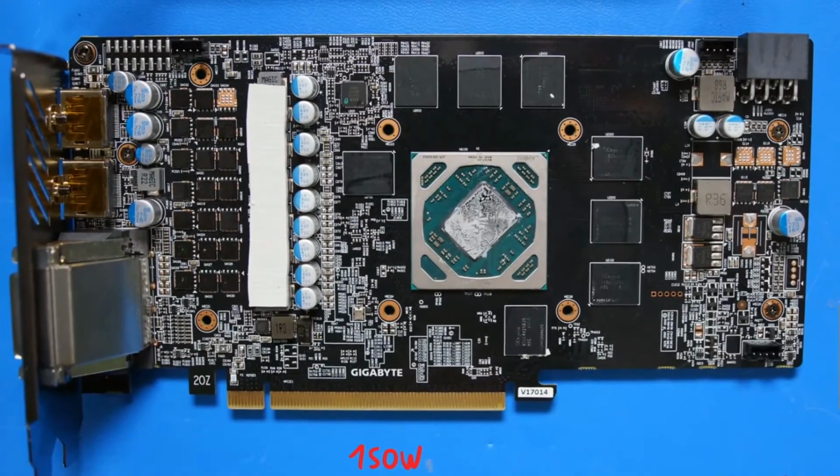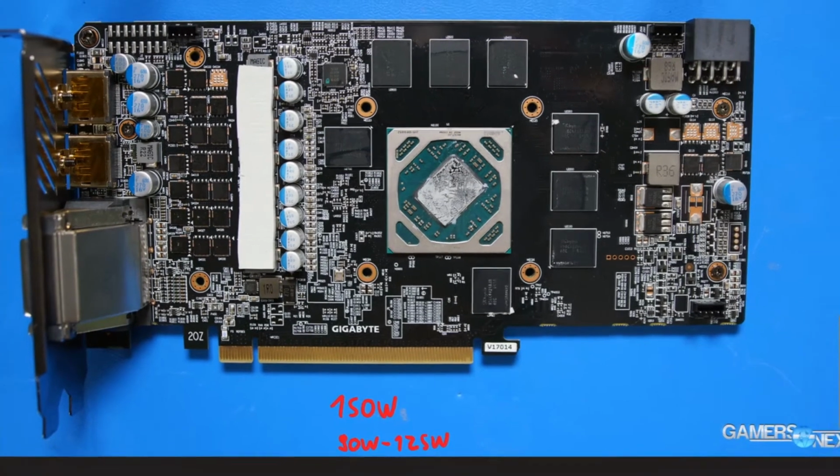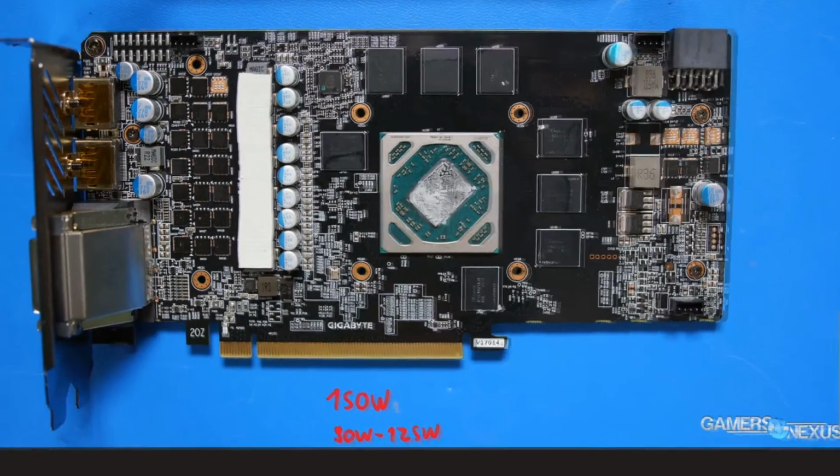There's also ways on AMD to get around the power limit, but that sadly involves all software tricks. So on AMD you were also able to make a custom BIOS in the past, but starting with either Vega or Navi, they also started to encrypt their BIOSes, so you can't make a custom BIOS anymore. It does work with Polaris still, which this is an RX 570, the picture is from Gamers Nexus, by the way.